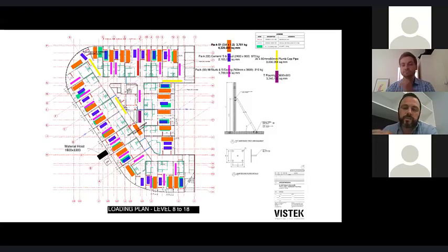Yeah, and look, I don't want to hang around too long on this slide because we want to keep to the time frame, but when we talk about costing of the hotel versus an apartment block, this is a very important point, because every wall on both solutions is a fire-rated, acoustic-rated wall, whereas if this was an apartment, you would not have an apartment the size of a hotel room. Your apartment would spread over at least 2 of these walls, if not 3. And then when you look at the concrete solution of a 9x9 grid, most of those internal walls are non-load bearing, just put in stud work with 10mm plasterboard, and that's it.